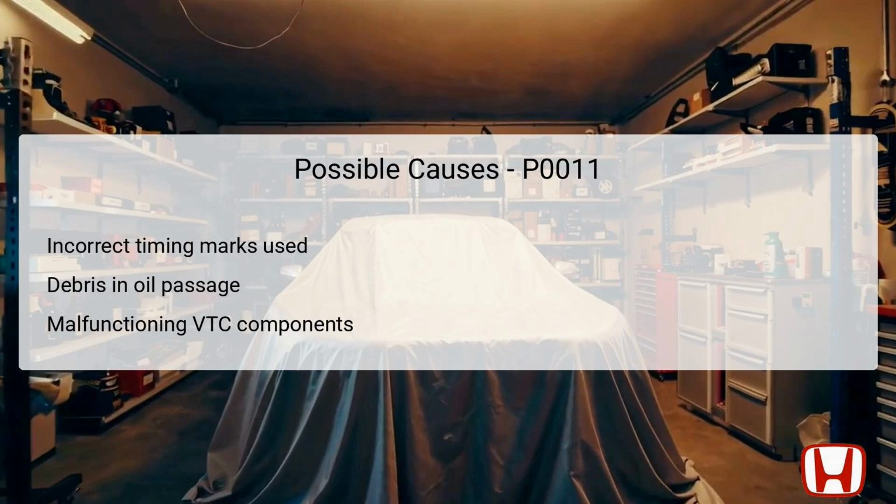Lastly, any malfunctions in the VTC components, including the actuator or solenoid valve, can impair the adjusting function, causing the advanced phase angle to exceed acceptable limits. Proper diagnosis must consider all these aspects to accurately pinpoint the issue.